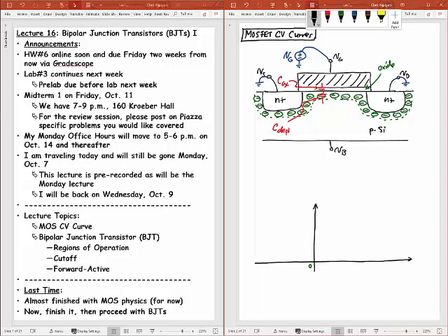And so I didn't finish this. This is going to be sort of the capacitance that I see associated with the gate. And this down here is going to be VGS, or just VG in this case, because both the source and the drain are grounded. And so when I'm at 0 here, what I'm looking at is a capacitance that is a combination of two capacitors, and I guess one of them is going to be Cox, so I'll just write Cox in right here. That's Cox on this capacitance scale. And the other one is going to be some depletion capacitance.